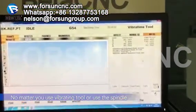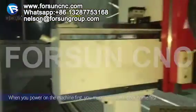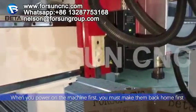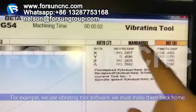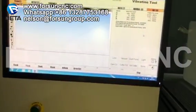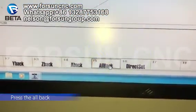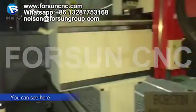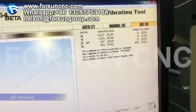No matter whether you use the vibrating tool or the spindle, when you power on the machine first, you must make them go back home first. For example, we use the vibrating tool software. We must make them back home. Press all back. You can see here, they are all moving.